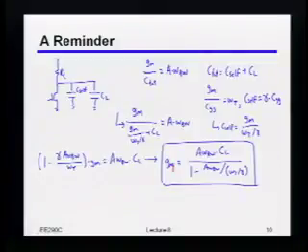Half omega t, yeah, exactly. You basically have to be operating at half of the intrinsic bandwidth of the device, right? That's why I really like this expression, because it quickly tells you, without knowing anything about what circuit you're building, that if I need to be operating at half of the intrinsic bandwidth, ballpark, I can take all of my very simple calculations, multiply them by 2, and I'll be very close to the real answer.